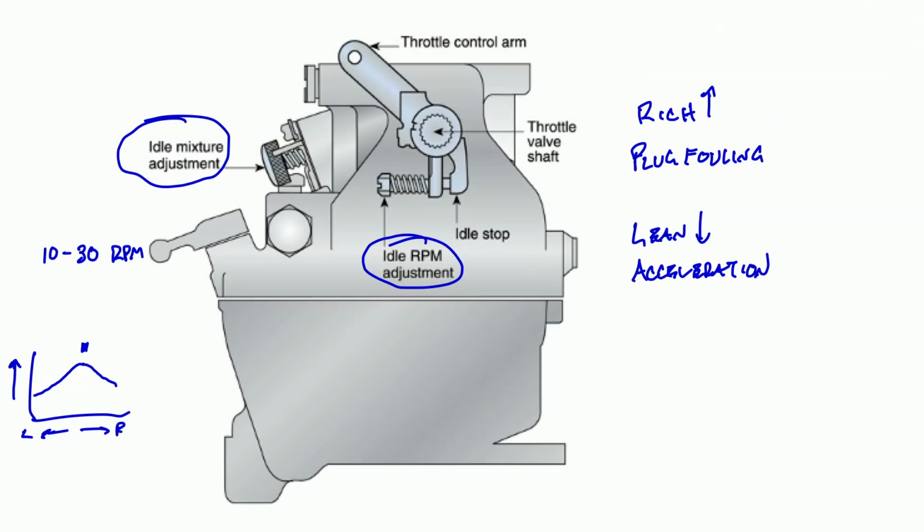So what happens is as the fuel mixture starts to lean out, once we cut it off, we actually briefly pass through our stoichiometric value, which produces more power, right? Pretty straightforward, and then our power dies off. So when we pull that, we're looking for that slight increase in RPM, because what that's going to show is that we are running just rich of stoichiometric. We pass through and we get a little bit, and then we die off.